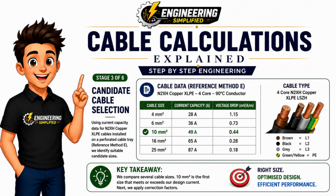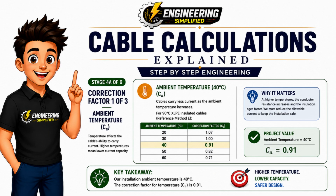installation conditions. Now that we've selected an initial cable, we need to check whether it can actually carry the required current under the conditions in which it will be installed. Manufacturers publish cable current ratings under standard reference conditions. However, real installations rarely match those ideal conditions. That's why we apply correction factors. These factors allow us to adjust the cable's current carrying capacity to reflect the actual installation environment.